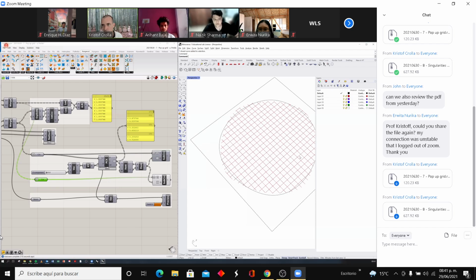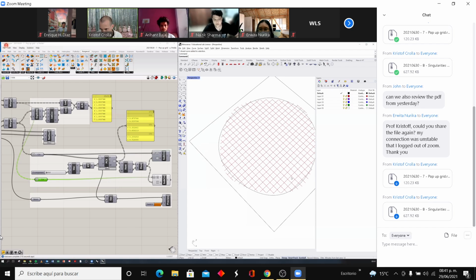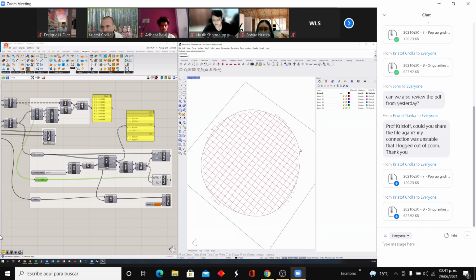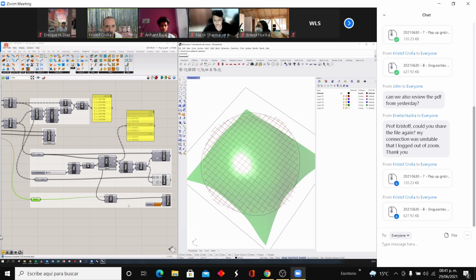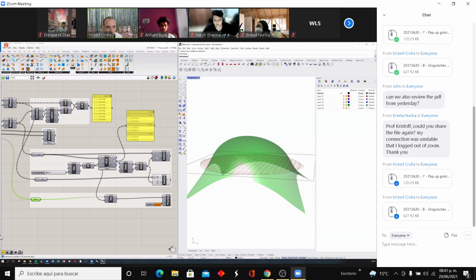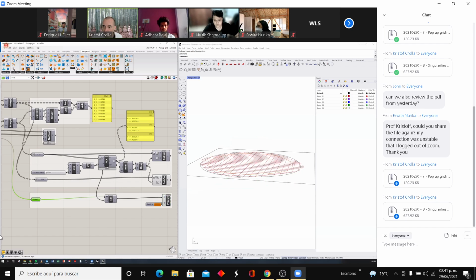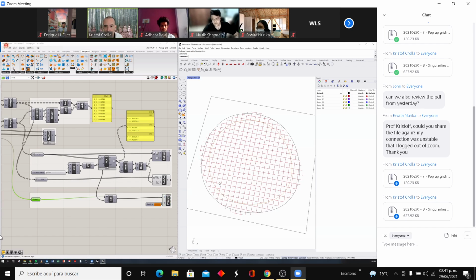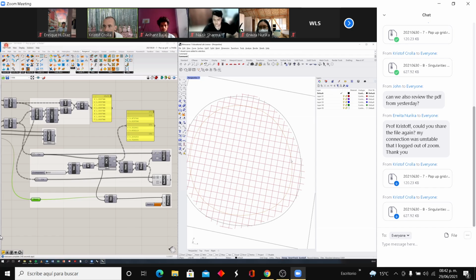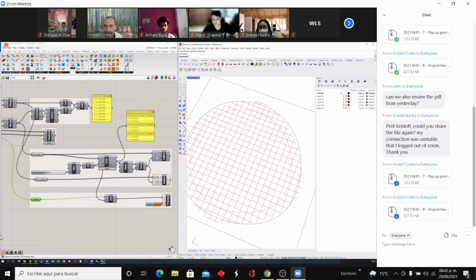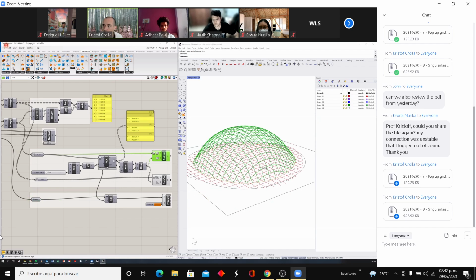And that's quite interesting, because you see there's actually not that much length difference between our bounding curve and the grid, but it's not identical. Another thing that helps in identifying exactly where our surface hits the ground is to intersect the mesh with the same plane. Right now you see that's where our foundation line is going to be. So this flat grid that we have produced here will eventually be pulled to that orange line to produce this grid that we have.